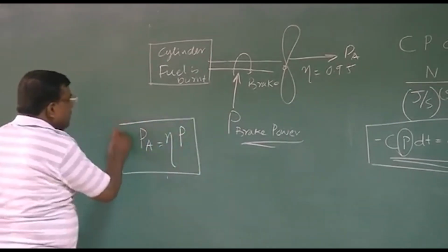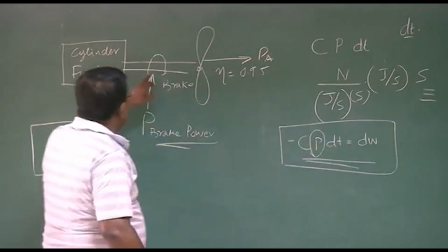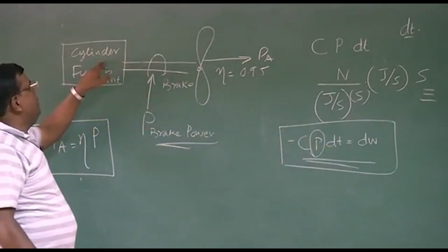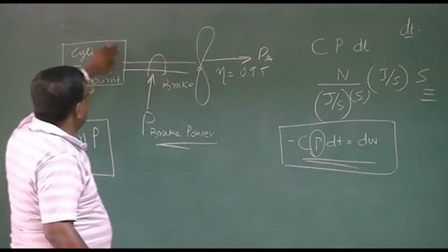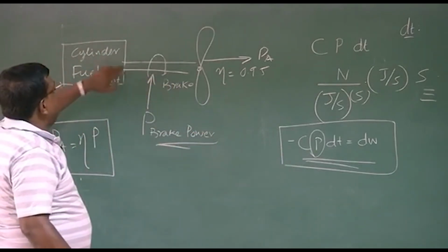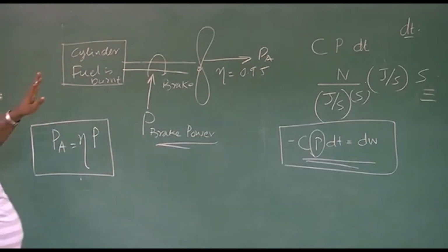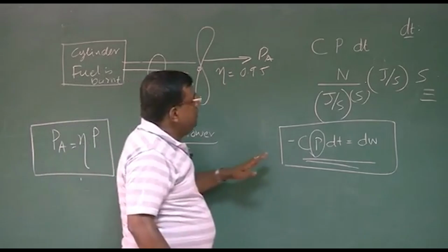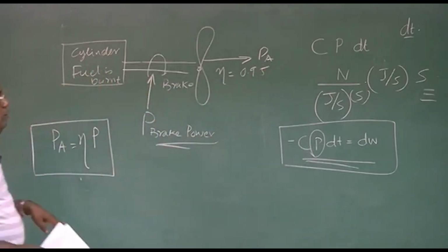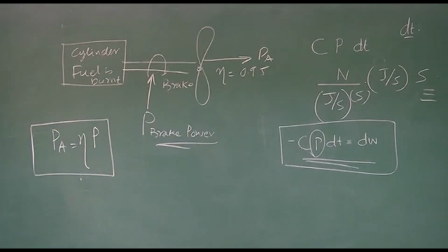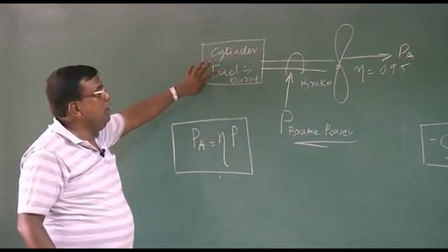This is extremely important. So when you are talking about dW, I am concentrating on the power here, so I am linking myself to this. That is why C, the specific fuel consumption, is a property here, as well as having some relation with the environment. I am stressing that this power is not the power available. This power is the power at the brake, right? Why? Because we want to relate range or endurance via the fuel consumption, right? So we are concentrating here.